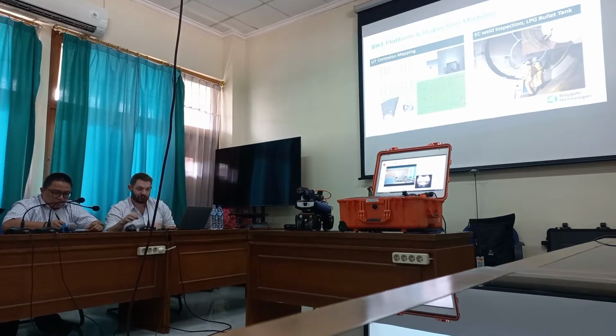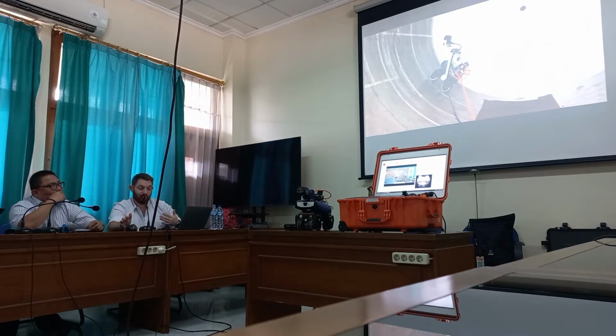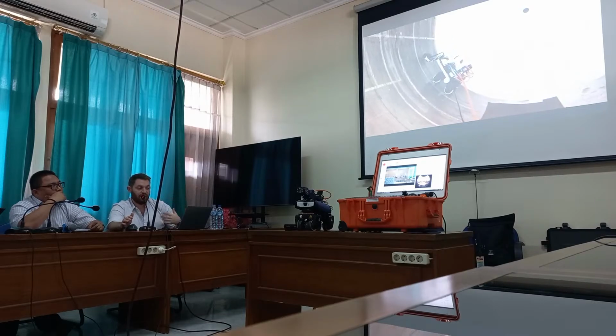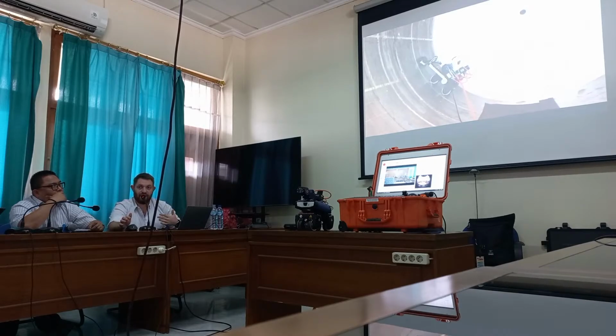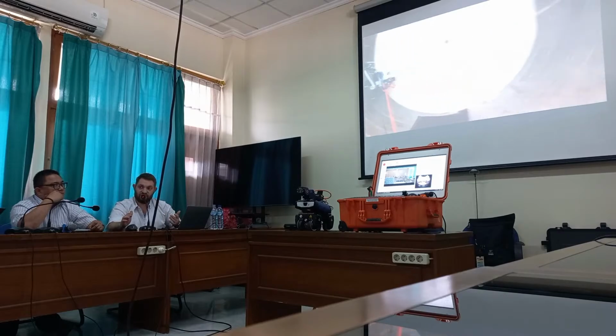And this is our eddy current inspection. So we've got another arm that mounts to the robot that again is fully controllable from outside of the system, from the control station. And from here we can mount different types of tools. So if we want to put on phased array or TOFD or eddy current array or PEC or some other form of tool, all we have to do is 3D print up a bracket that holds that, and we can go and perform those inspections.